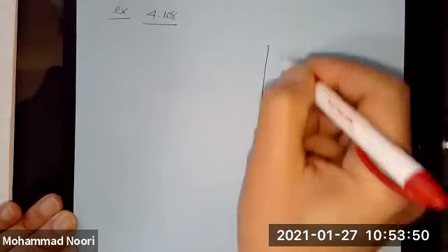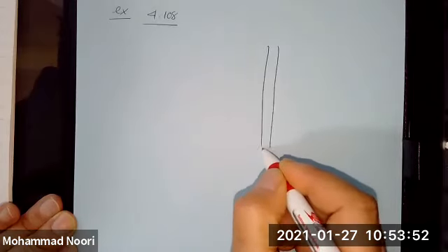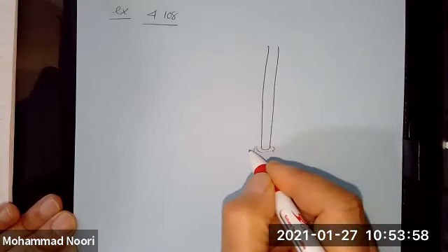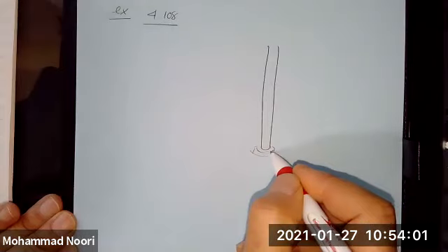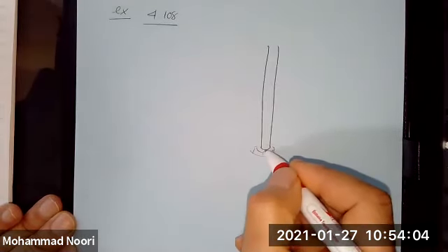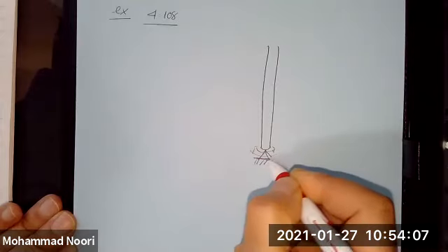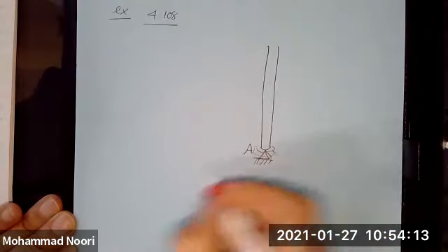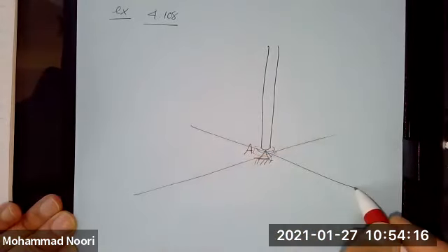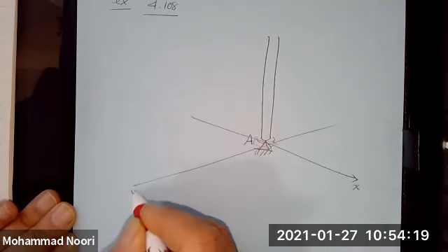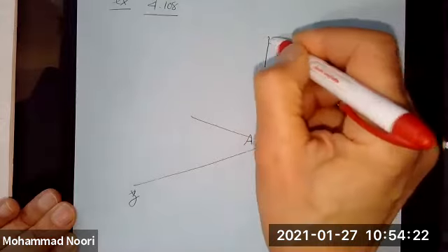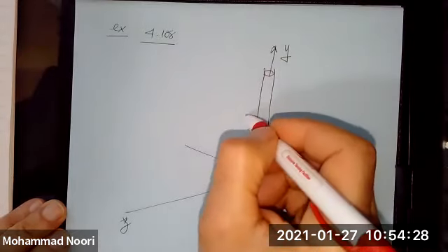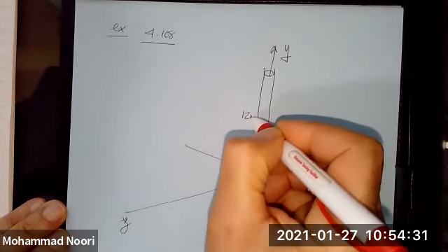So, what is this problem? You have basically a ball and socket support here, support system, which is basically like a three-dimensional hinge, allows rotation in any direction, but prevents translational motion. So if this is X, this is Z, this is Y axis, okay? The length of this, or the height of this, is given as 12 meters.